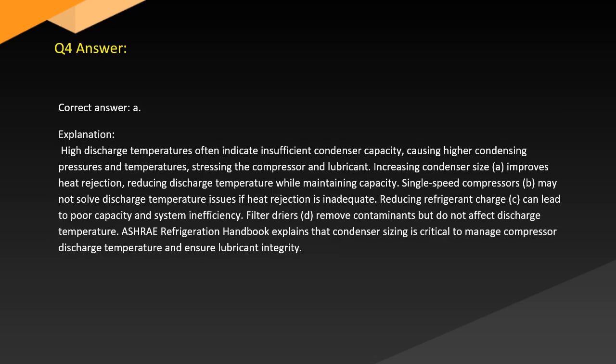Answer. Correct answer A. Explanation. High discharge temperatures often indicate insufficient condenser capacity, causing higher condensing pressures and temperatures, stressing the compressor and lubricant. Increasing condenser size (A) improves heat rejection, reducing discharge temperature while maintaining capacity.